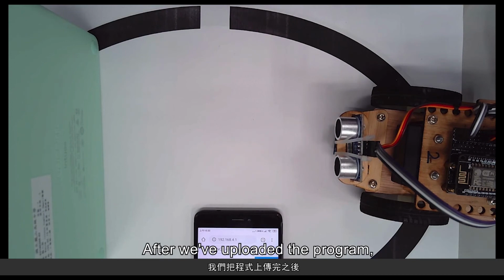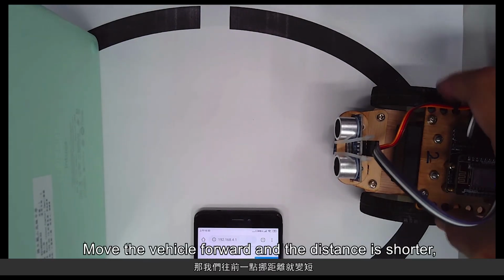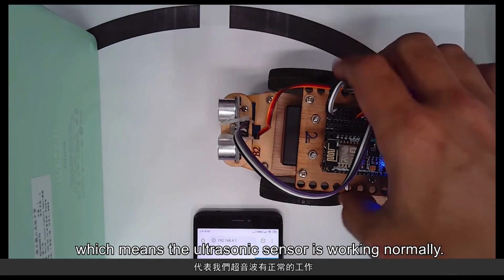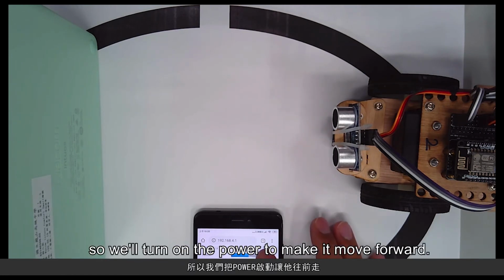After we've uploaded the program, we'll open the browser in our smartphone and connect to the network. You can see that the distance measured is 19. Move the vehicle forward and the distance is shorter, which means the ultrasonic sensor is working normally. For the writing of our program, when the distance is less than 10, the vehicle will stop. So we'll turn on the power to make it move forward.